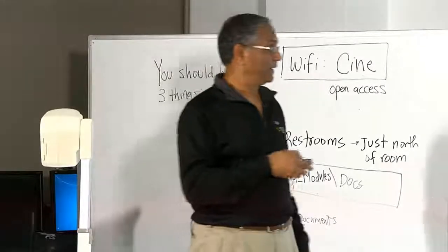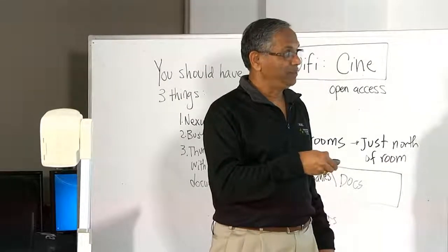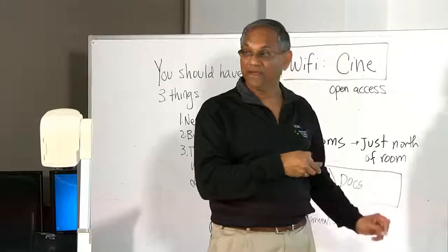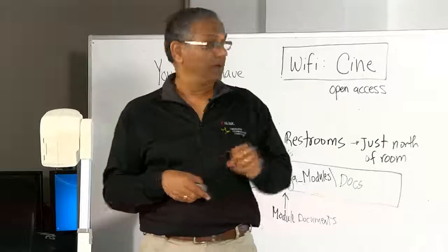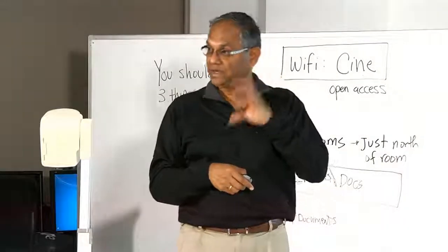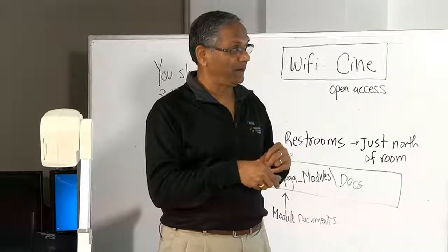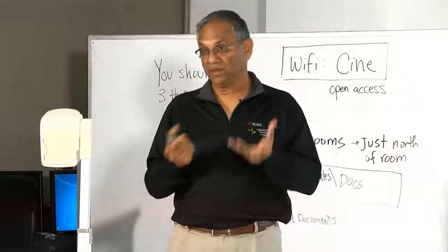Okay? And then you have the input outputs, which can go to the dedicated pins. If they are dedicated pins, then you do not need to give constraint files, or constraints, for those pins. The tools will pick it up. If you are using user I/O pins, you must provide the constraints, otherwise it will give you an error.